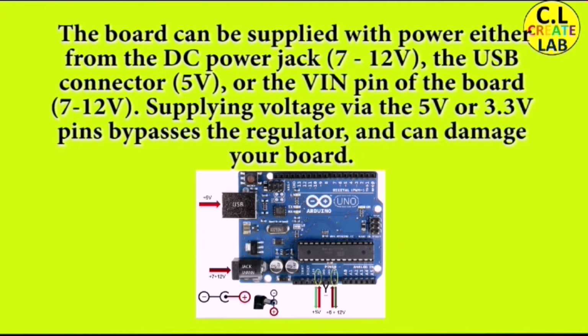The board can be supplied with power either from the DC power jack, 7 to 12 volts, the USB connector, 5 volts, or the VIN pin of the board, 7 to 12 volts. Supplying voltage via the 5-volt or 3.3-volt pins bypasses the regulator, and can damage your board.